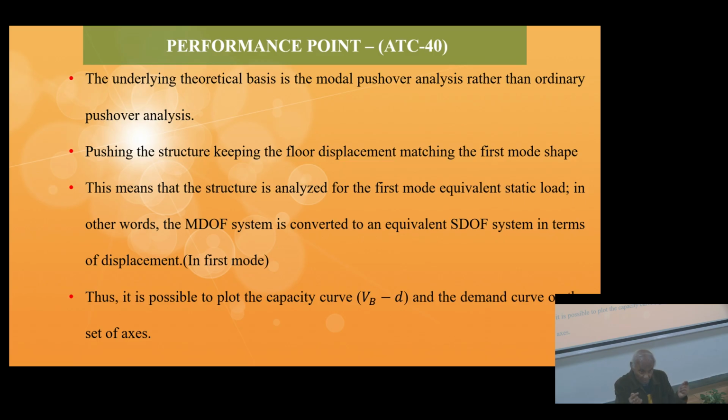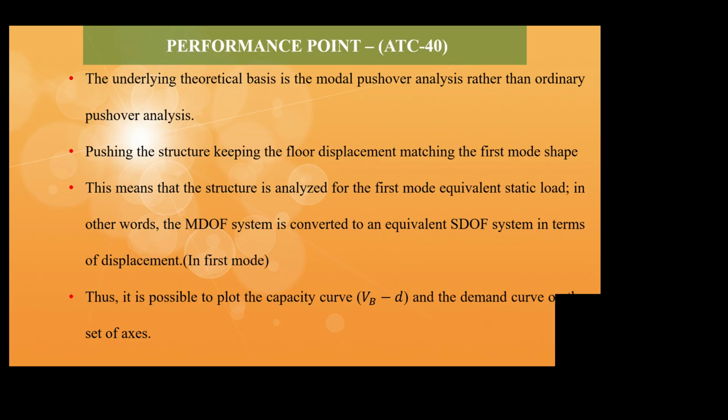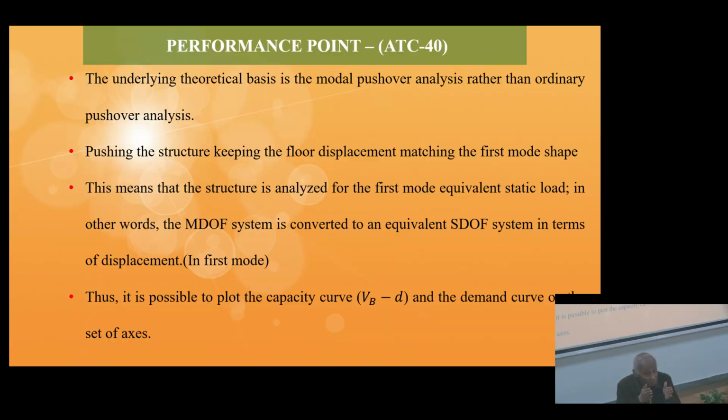So I am considering an equivalent stiffness of the system, by way of defining what is the force required to provide unit displacement at the center of the beam where I have lumped the mass. This is my basis. It may be far away from the actual, or it may not be. But what I am saying is that this is how they used to do it.